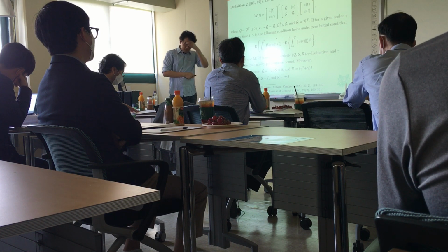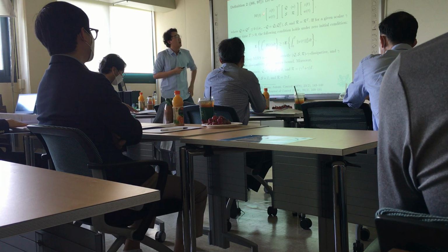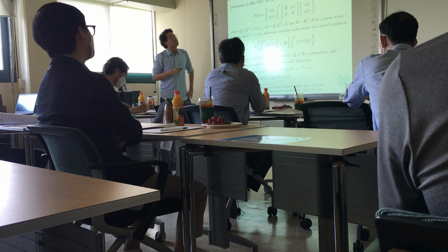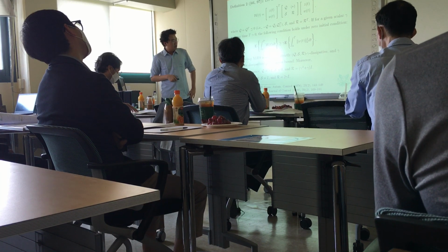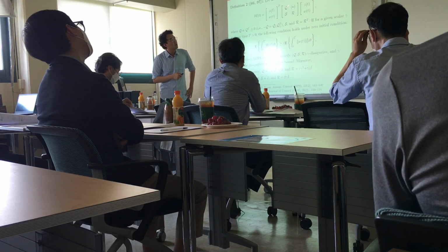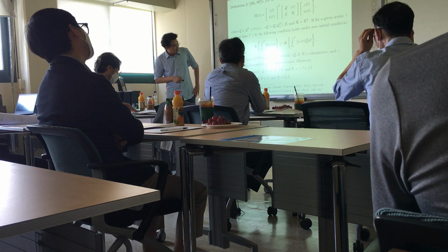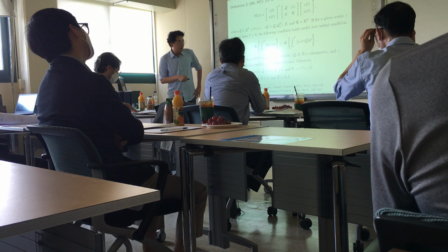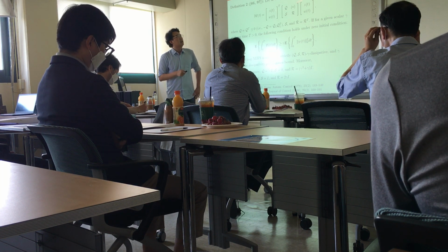The dissipative performance is characterized by the quadratic energy supply rate. By choosing some suitable matrices Q, S, or R, we can obtain the H-infinity performance and passivity performance from the dissipative performance.